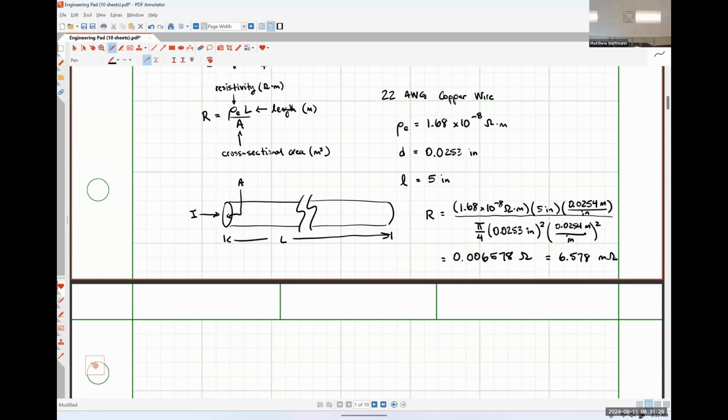Now, if you're working at an industrial plant or something like that, and you're having to set up a really, really long cable run to go from a control room out to some sensor, the length of that wire might be long enough such that the resistance is actually appreciable. And so those are things that you're going to have to take into account when you're dealing with practical electric circuits. Everything that we're doing in this class is kind of a lab scale thing, so we are going to treat all wires as if they have zero resistance, or they are a short circuit.